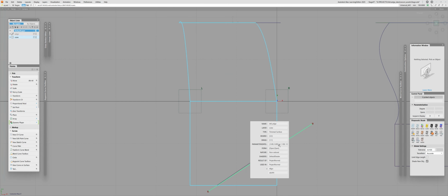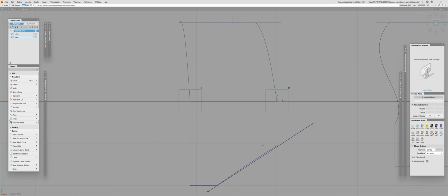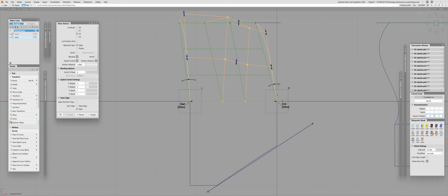If you check it, you're going to see that by default it still shows you the original boundary. So you don't know how it reparameterized that, but it does, and instead it's just taking the resulting vector of it. This is not beneficial. The reason why it's not beneficial is because it's uncontrollable. You have your angle, you can move it, yes, but these 0, 0 parameters are not really tied to anything.